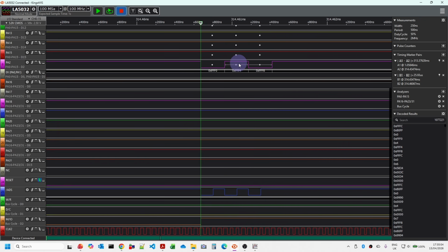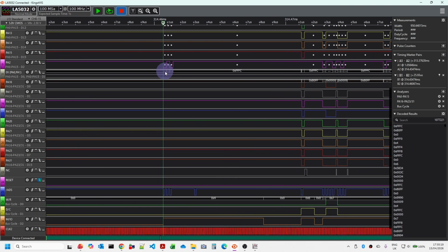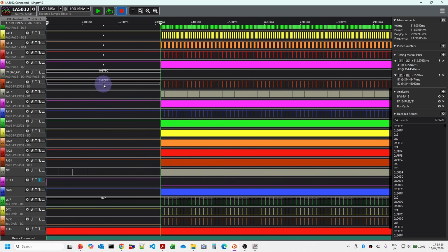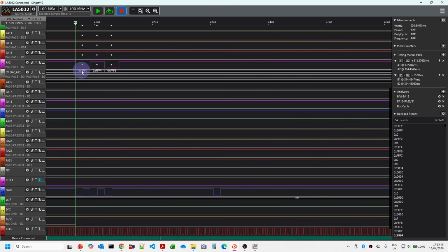So we've got our first couple of instructions here. Let's see what's happened. It's actually reading FFF0. This is the reset vector, where the Intel processors look at the very top of memory. And because we know that the top address bits here are also going to be all set to 1s, just because we've only got address 31 and then 16 to 23, this is effectively FFFF. So it looks like we're reading 4 bytes from F0, then another 4 bytes from F4, another 4 bytes from F8, and then something happens.